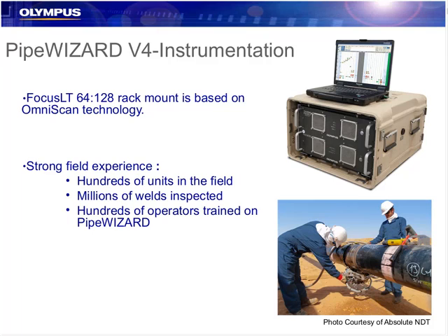This unit runs basically on a band, a CRC type band. It's kind of hard to see in the picture here. We'll see if we have it a little bit later. This is the same type of band that an orbital automatic welding system would run on. And the reason for this is when we looked at the pitch-catch technique, it's very important that the mechanics of the system can hold the probe to a very tight position. If we're only using one beam to fit in on a very focused zone, we need to ensure that probe doesn't have a lot of movement.